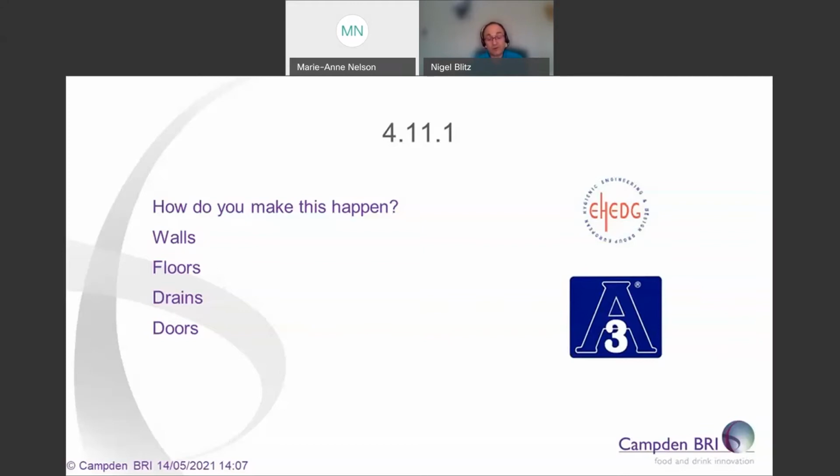Doors play an integral role in the building design by helping to segregate production areas while presenting a barrier to contamination such as dirt, insects and other pests and vermin. However, as food products have to move through doors, there is a possibility that contamination can drain, drip, diffuse, or be drawn into the production from door surfaces. Doors must therefore be hygienically designed.